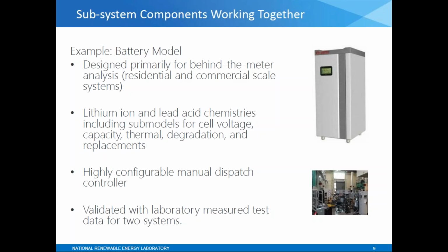At the moment, we've got this designed primarily for behind the meter analysis, and what we've done is actually allowed a whole lot of different battery technologies to be represented. Each technology has its own degradation characteristics, capacity characteristics, ramp rate characteristics, and we've tried to represent those in the model. And then obviously the issue of dispatch can be really complicated with batteries. When do you run the battery? How does it fit with your load? What are the rules from the utility's perspective? And then we've done some validation of the battery model.